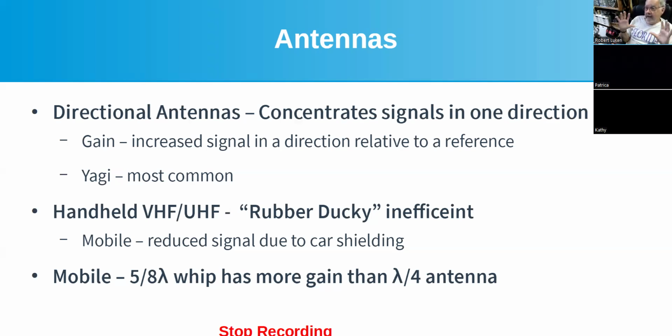The larger that surface, the smaller the watts per square centimeter. When you change that pattern into a very narrow lobe in one direction, that 100 watts is spread over a smaller area, so the watts per square centimeter is much higher. It's still only 100 watts.